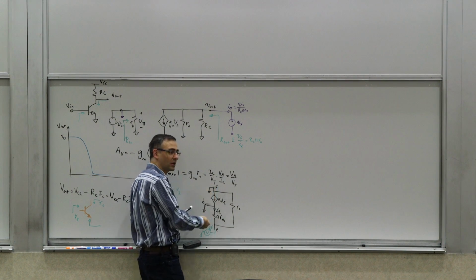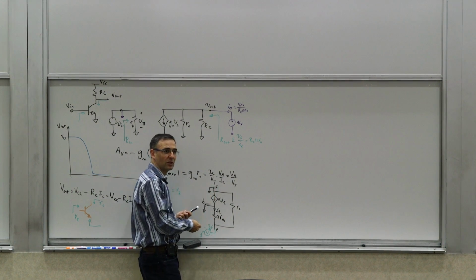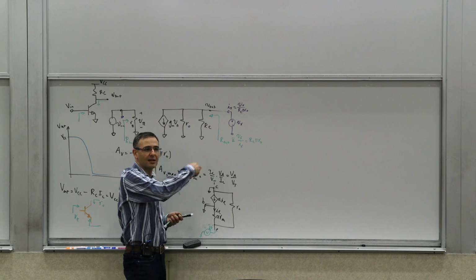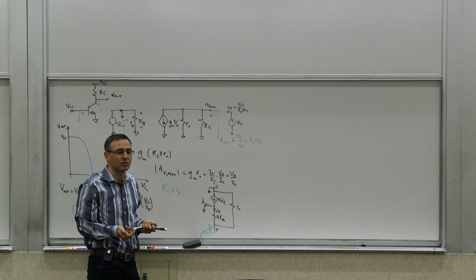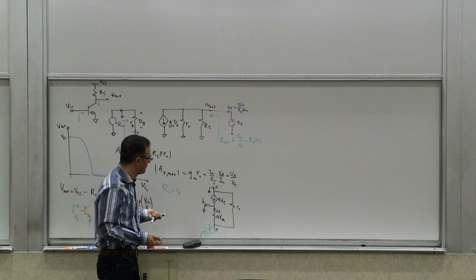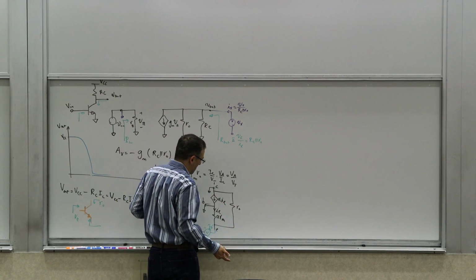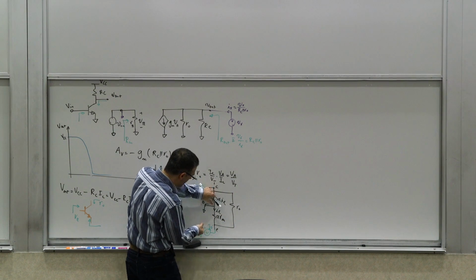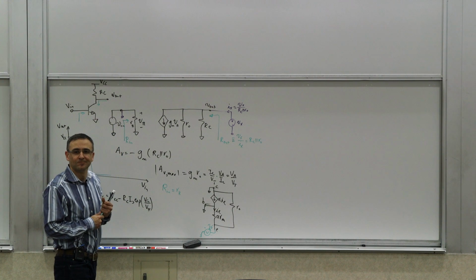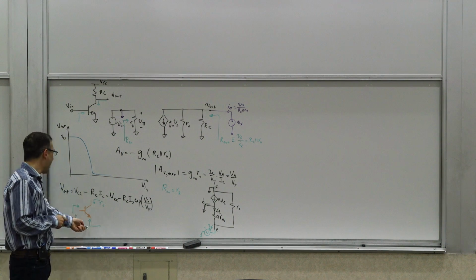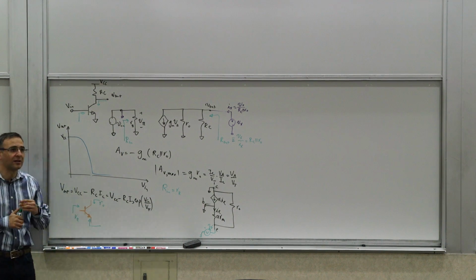But this current source is shorted across because it's shorted on both ends. So that current will flow inside the closed loop, so it wouldn't affect anything else. So that doesn't matter. So what else do you see? You see two resistors in parallel, alpha Rm in parallel with RO.